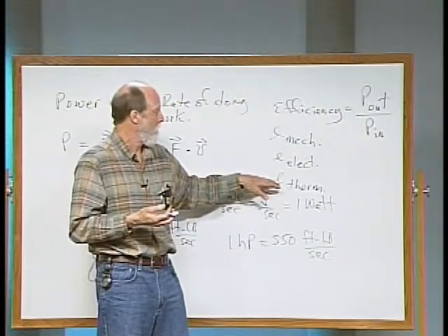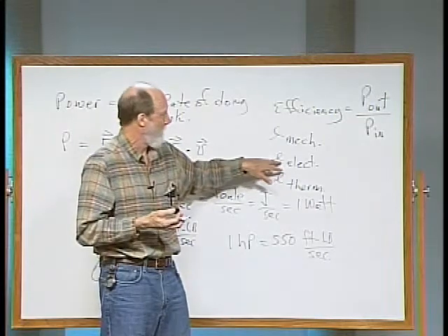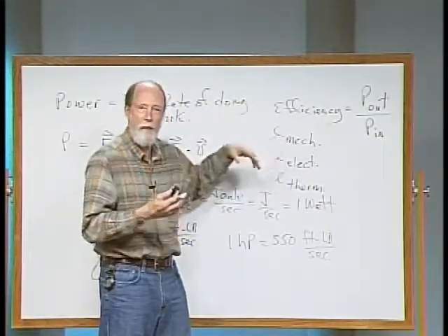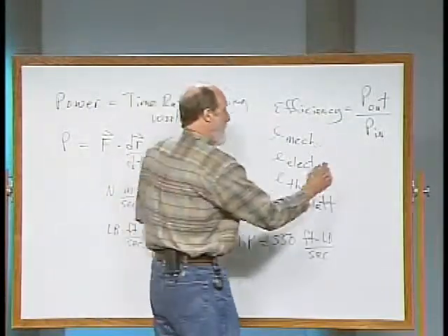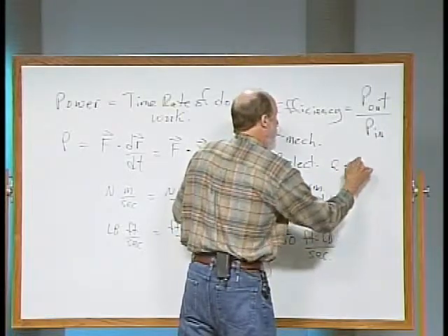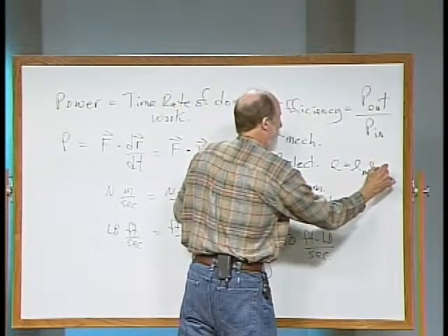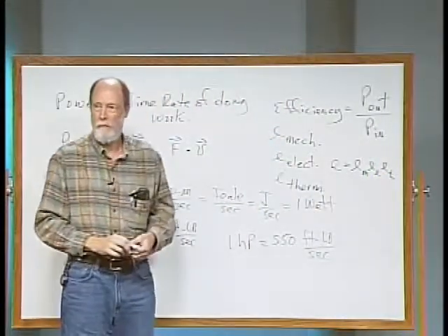You may have used some of that thermal energy then to generate some electricity, and there are losses electrically, and there are losses mechanically if you have, say, a power takeoff occurring. Then the effective efficiency is going to be equal to the product of these various elements of efficiency. Okay?